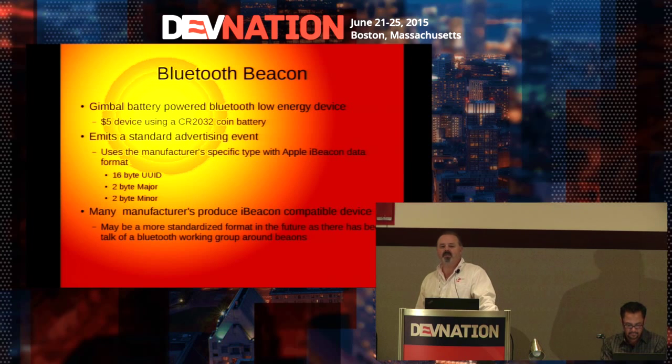And how it works is it emits a standard advertising packet. So in the Bluetooth low energy spec, they define several different data formats, and one of them is called an advertising packet. And there's several different types of advertising packets that dictate what the format of the data is. And the use case for that most manufacturers work with in terms of the beacons is it uses the iBeacon format that Apple is promoting. And that's tagged in terms of the type of a Bluetooth advertising packet is called a manufacturer-specific data. So it's completely arbitrary. So you really have to know what Apple has defined as the iBeacon format, to be able to identify it if you're creating a scanner that's looking for iBeacons.